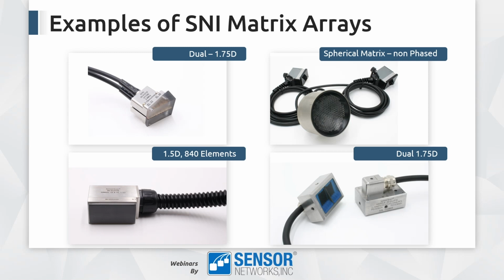This is actually an immersion transducer, so it would be put into an immersion tank, and then using the matrix array to achieve focal depth over a variety of depths in the part, as well as to linearly scan through the array and create one axis of scanning. And of course, the other axis is by the turntable in the immersion tank.